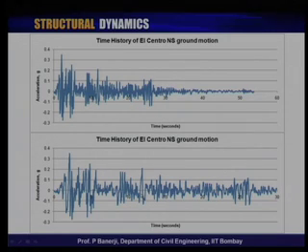So, therefore, time history is something where it is impossible to define a design ground motion history. What is done? I will explain that. If you have been working in an organization that does earthquake response analysis, you would have heard of design ground motions. These are called spectrum compatible ground motions.